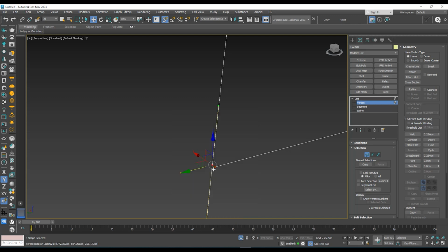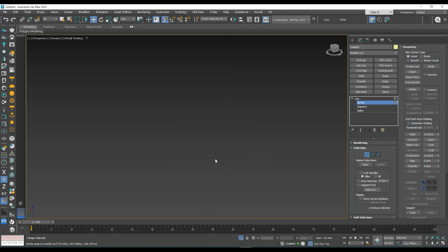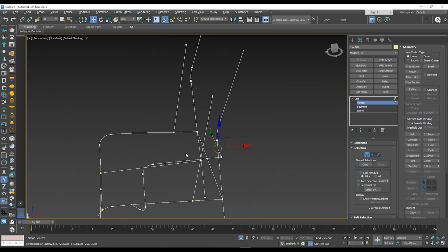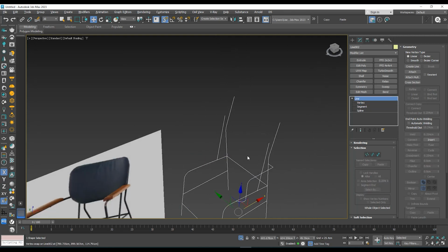So click here, then it not work actually. So another, you can select the fuse vertices. Okay, so fuse it, then boom, now these two parts are welded. So first of all weld vertex and then fuse vertex, or vice versa, you can fuse vertex and then weld vertex, you can do like this.